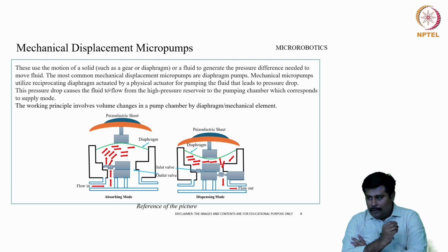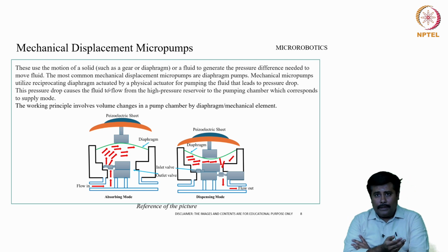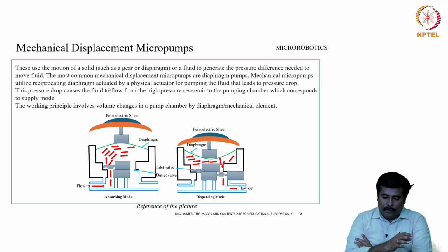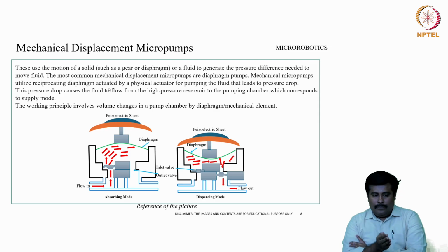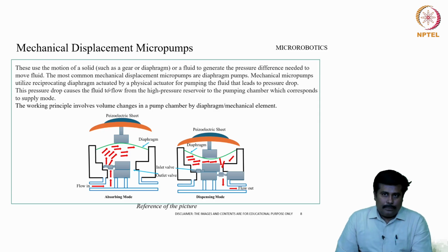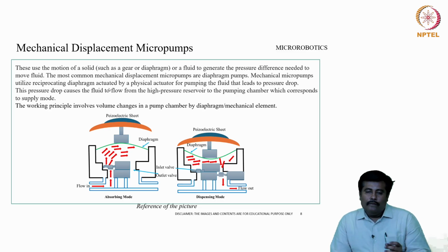When we talk about diaphragm pumps, there are wide varieties, either shape memory alloy based or piezoelectric based structures. A mechanical micropump utilizes a diaphragm actuated by a physical actuator for pumping the fluid, which leads to a pressure drop. This pressure drop causes the fluid to flow from the high pressure reservoir to the pumping chamber,